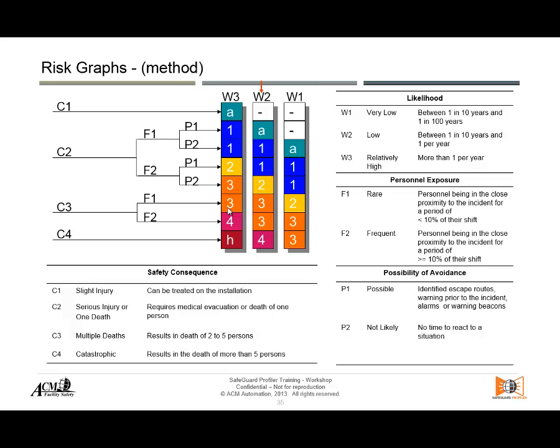So that would tell me, for example, here the W1 means the likelihood, how likely it is, and that is represented by the axis of the risk matrix of probability or likelihood. And then you see I don't have W4, W5 if there is a 4 by 4 matrix or a 5 by 5, right? I only extract a portion of the risk matrix. There is a place that needs a safety implemented function. Well, that's the place that I'm going to extract from that risk matrix.